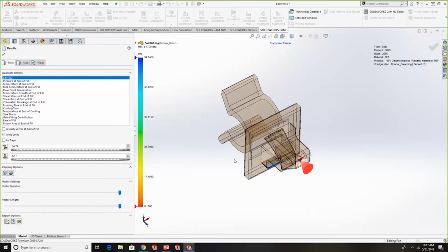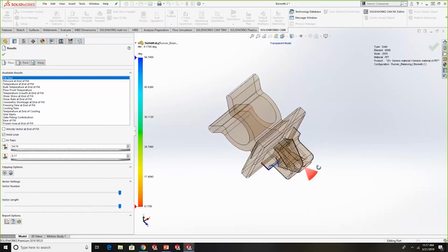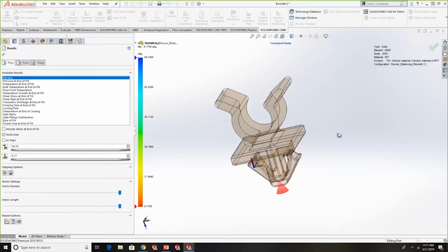It's not necessarily homogeneous. So if you've ever looked on the inside of a part or on the back side of the part, the side that your consumers aren't going to be seeing, if you know what you're looking for, you'll be able to find a weld line. And it's really important from a mold making or tool making perspective, because if it's a consumer facing plastic part, you want those weld lines not to be on the consumer facing side. So in this case, it's on the bottom, which is connecting. It's not really an issue to me.